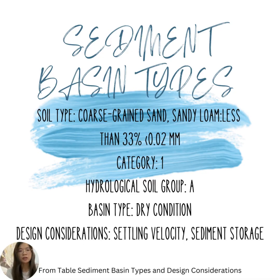First step, we need to determine the sediment basin type. For the dry condition, the soil type is coarse-grained sand, sandy loam, which is less than 33%, less than 0.02 mm. And the category is 1. The hydrological soil group is group A. And then the design considerations, which are settling velocity and the sediment storage.